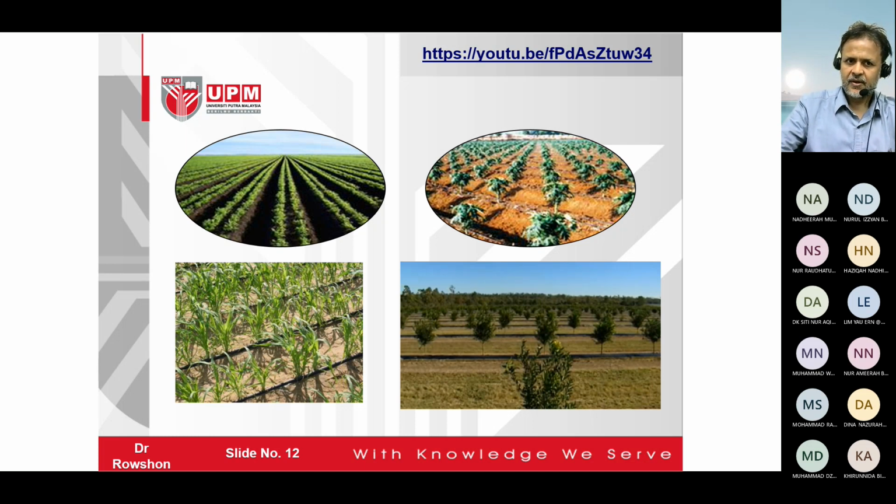Another one I told you, AW, is it? AW means weighted area. Weighted area is determined by DW. DW is the emitter weighted diameter. When you buy the emitter, the emitter will give you this DW specification. Then we can calculate pi d square by 4.